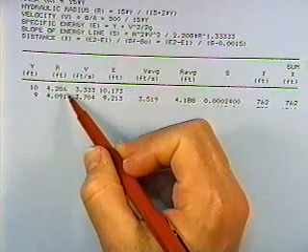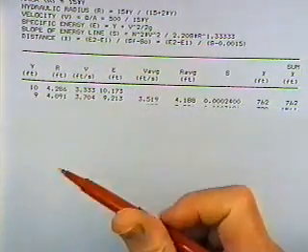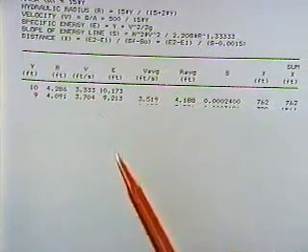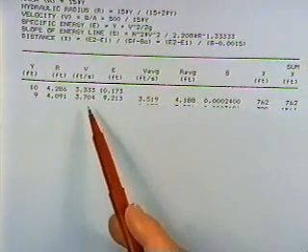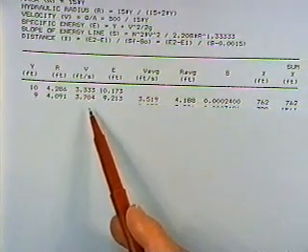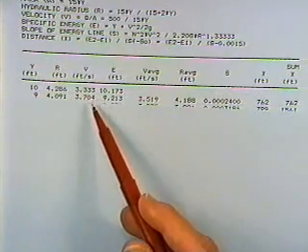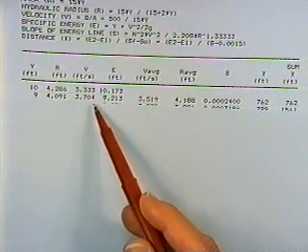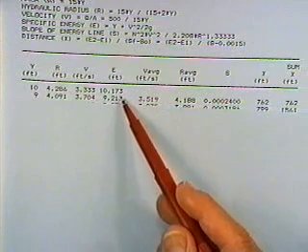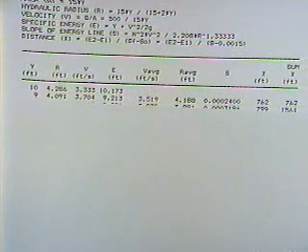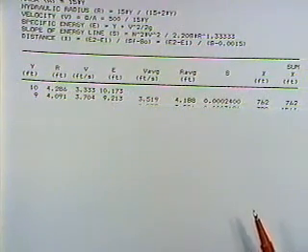Then the wetted perimeter is just the bottom width plus 2 times the depth. We can divide one by the other, get the hydraulic radius each time, and divide the 500 cubic feet per second discharge rate by the area to get the velocity. And then specific energy is just the depth plus the velocity head. And so velocity squared divided by 2g plus the depth. And we've got the specific energy upstream and downstream.